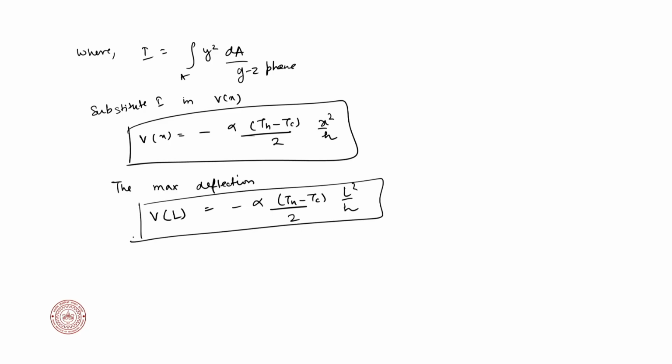So what we have done for a bimetallic strip, actuated in this case, is that they will have two different expansion coefficients. You can solve a similar linear thermoelastic model with two different alpha values and get the solution. To summarize everything together, we have a body that is expanding due to a temperature difference.